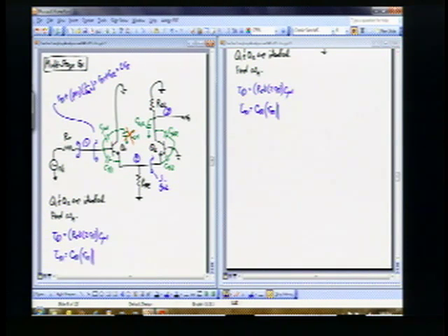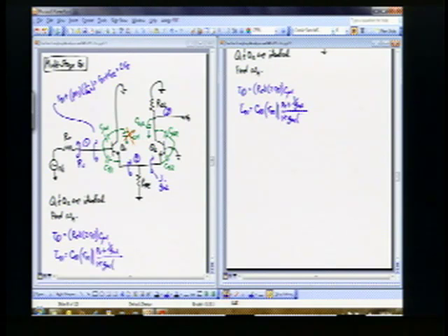Okay, all the resistance I see looking out that way, that's just RS. So I have RS there, plus all the resistance I see looking out in that direction, which is technically REE in parallel with 1 over GM2, but I'm just going to neglect the REE because that's generally a very large resistor if it's used in biasing. So I'll just say this is times 1 over GM2 there, and then all of this divided by 1 plus GM1 times 1 over GM2. Okay, so that's what I would have to calculate to get this driving point resistance for tau pi 1.